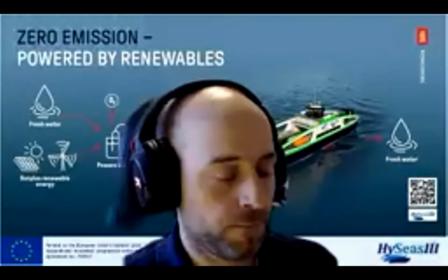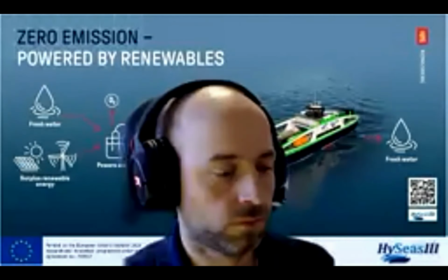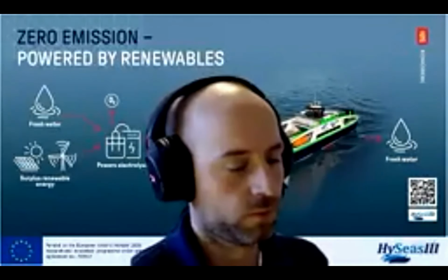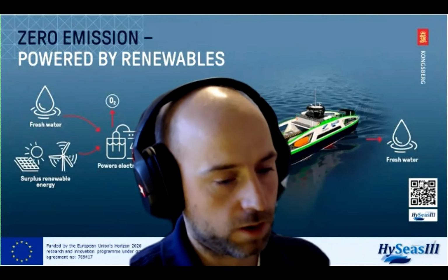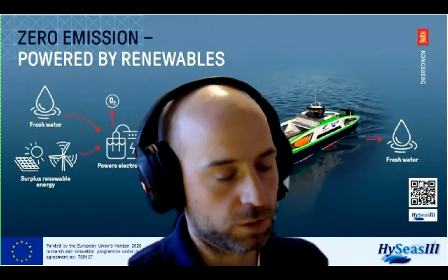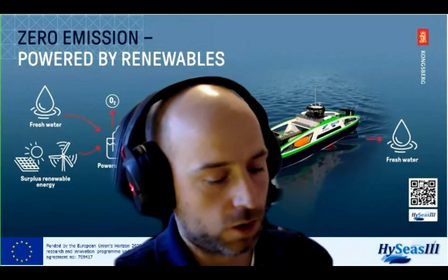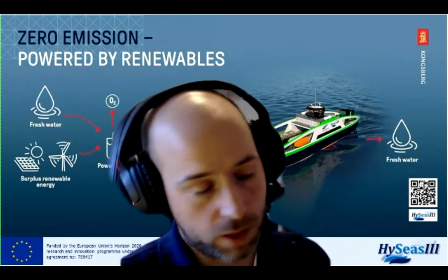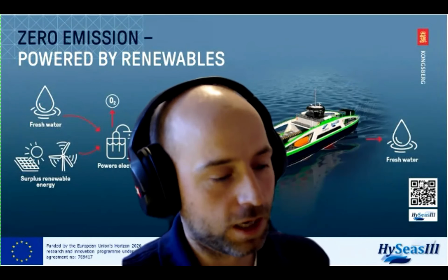Thank you. I was interested, is there a big difference between fuel cell efficiency, system efficiency, and vessel efficiency? So the number of 51% is vessel efficiency, as I now understand. Yeah, it's basically the theoretical kilowatts per kilogram of hydrogen versus what is produced on the actual main bus. But if you include the batteries, whether they are charging or discharging will directly affect this kilowatt efficiency.